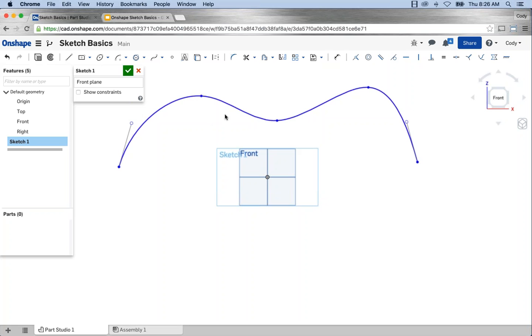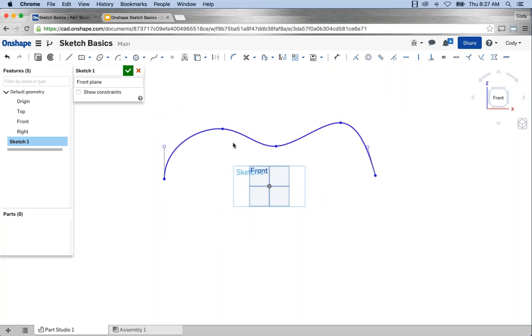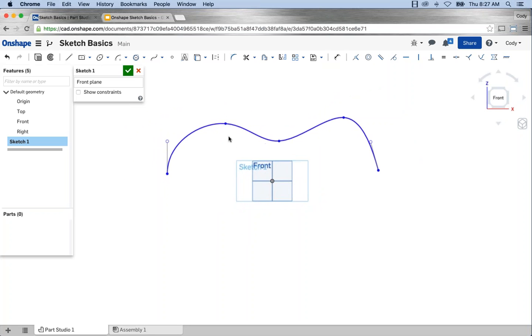Now, I mentioned before, the fewer points you have, the better. Sometimes, just a 2-point spline with defining the ends is more than enough. With multiple point splines, the more points, the more difficult it is to maintain and to keep it smooth. So that's splines.